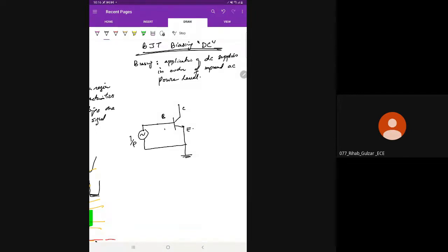And we also know that the voltage between base and emitter is known as VBE, and it is nearly equal to 0.7 volts. Now the question is, if the input is like this, अगर ये input ऐसा हुआ, एक साइनोसाइडल सिग्नल हुई, और इसका पीक एम्पलीट्यूड है 0.3 volts. Now see, 0.3 volt is lesser than VBE. VBE is 0.7 volt and your input signal is 0.3 volt.